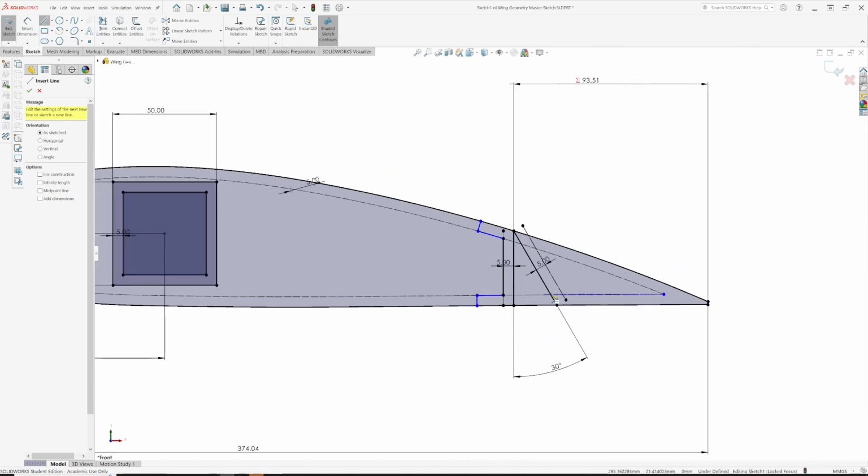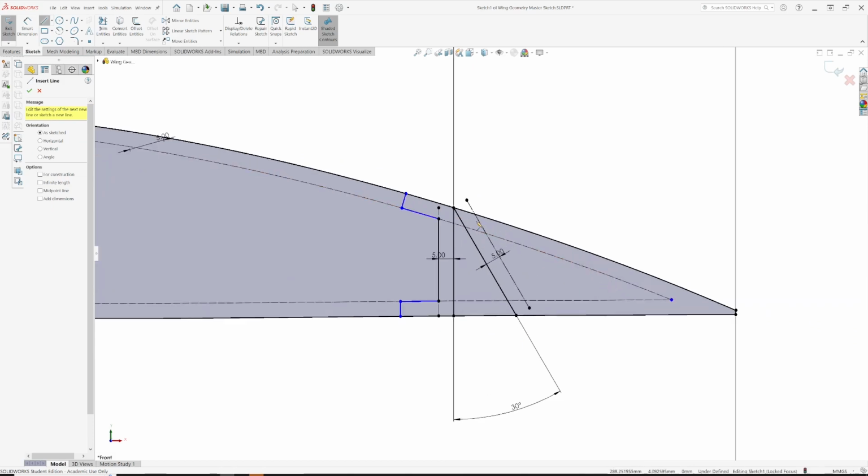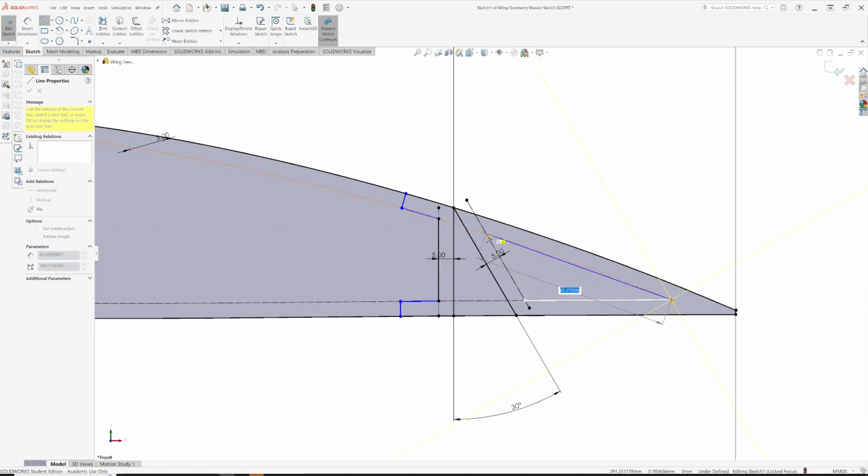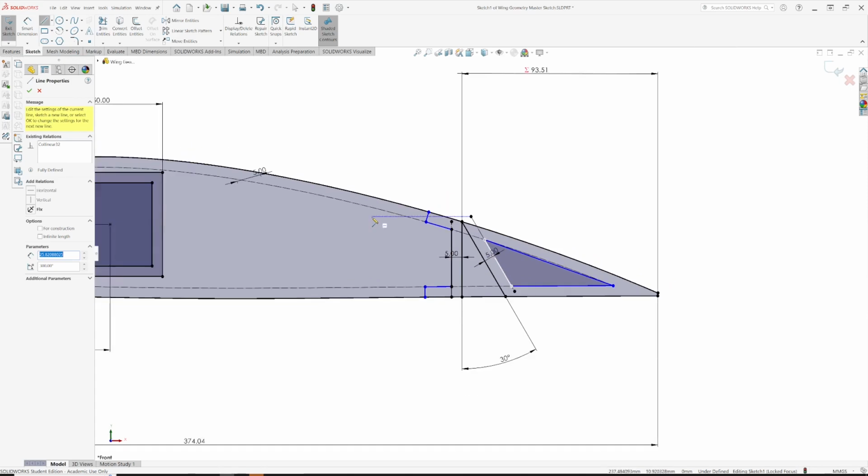While we're here, let's finish off this. This is going to be made out of foam board, so we want it to be a 5mm shape that we can fold up into a sort of triangle. So let's cut out the middle of this triangle properly. If you notice, when I made that triangle, it went a different colour grey because SolidWorks recognised I connected it all up. If I'd missed that last point and it hadn't joined up, it wouldn't have gone grey. This one hasn't gone grey because we've used different lines to do it, but we'll check in a minute that it's worked.